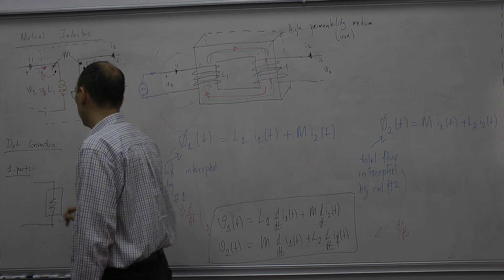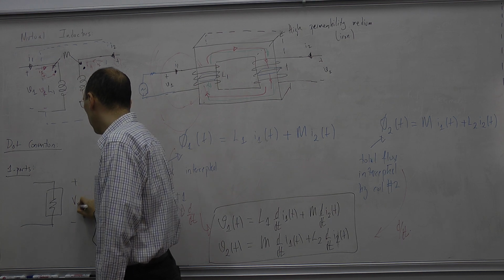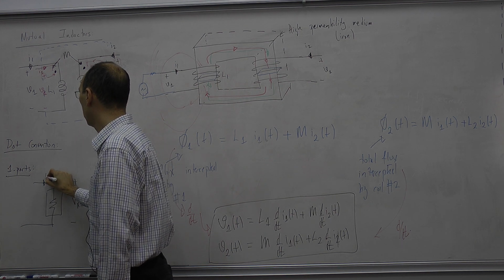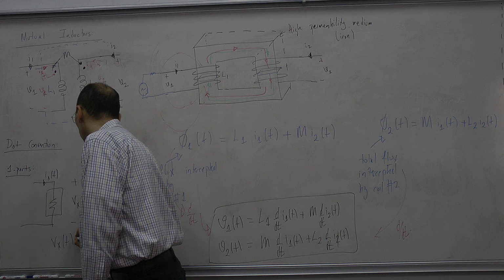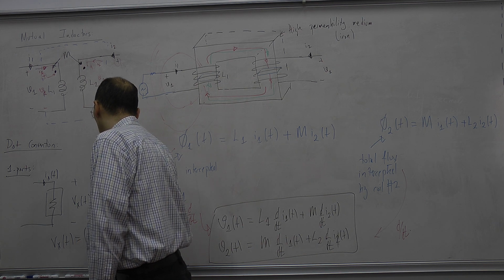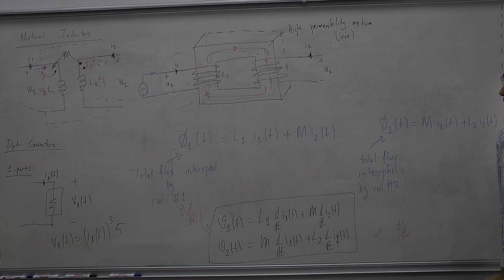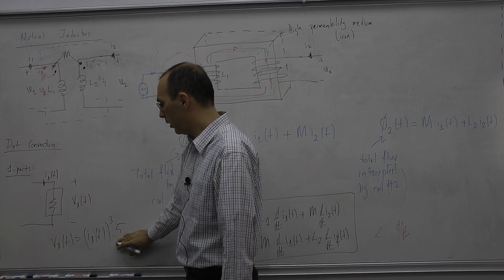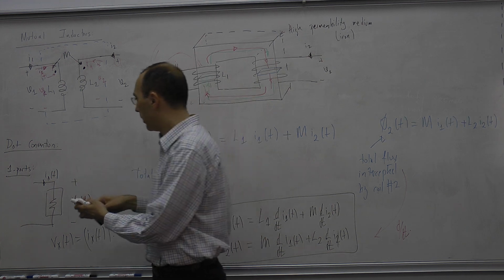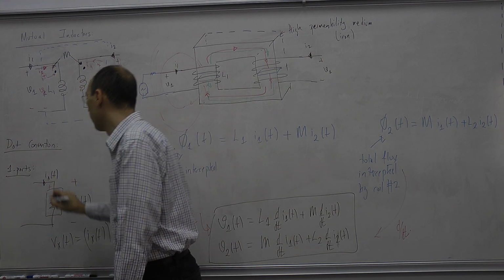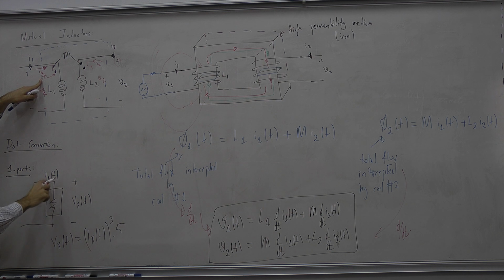So if you have a resistor, let's say some kind of a resistor over here, now if you define a mathematical relation between this voltage and resistance's current, let's say that Vx of t is Ix to the power 3 times 5. I'm just making this up. If we have something like that, this equation is only valid when Vx, Ix are assigned like that. Again, current is entering to the plus terminal. In both cases, currents are entering to the plus terminal, plus polarity.